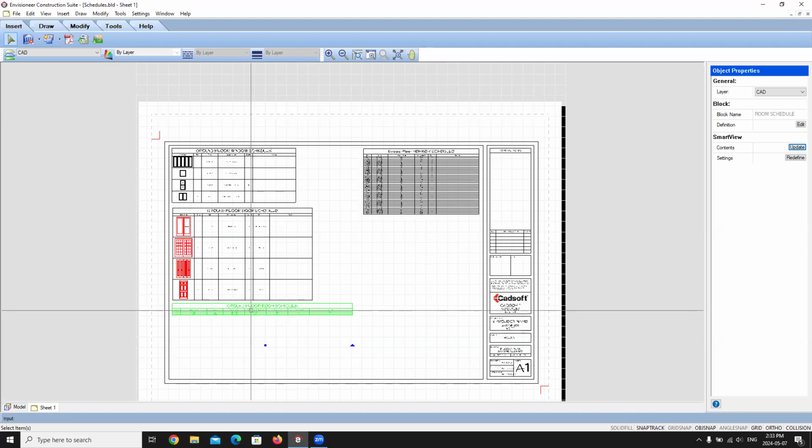When you create a door, window, or member schedule, the doors, windows, or members in your model are tagged with schedule marks that correspond to information listed on the schedules. You can choose not to tag the elements if you prefer. To report floor, ceiling, or roof surface framing within a schedule, you need to first convert the framing to members using the Convert Framing to Members tool.